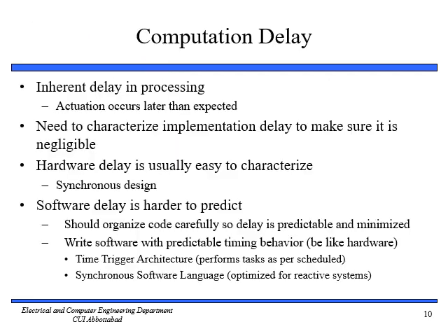Time lags are of critical importance in control systems. Delay results in control signals being applied later than desired. Obviously, too much delay will result in performance degradation. The effect of delay can be accurately analyzed. For the designer of an embedded system, there are two important conclusions. First, analyze at an early stage in the design process the hardware platform and the processor speed relative to the phase lag that can be tolerated. Second, organize the software so that only necessary computation occurs between the time the sensor signals are sampled and the time the control signal is output. We can move all the possible computation outside of this critical path. So that was about computational delay.